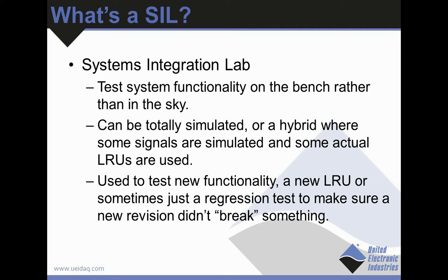There's simulated signals and the actual LRUs in a series of relays that can determine which one is online at any given time. And these are used to test new functionality of new LRUs or also to regression test any changes that are made in an LRU or a flight computer software just to make sure the new revision doesn't break something.